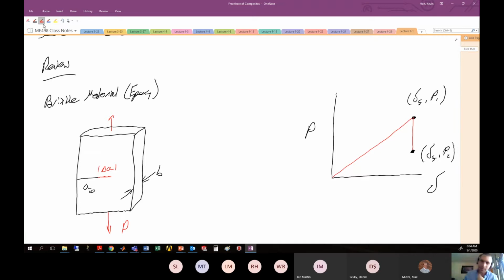All right. Then if we unload this sample immediately after this fracture has occurred, because we're purely elastic and there's no plasticity in the sample, it unloads right back to where it originally started here at the beginning. So this is kind of our load displacement. And in this particular instance, here's where our crack propagation delta A has occurred. All right, so it occurs when we lose that load.